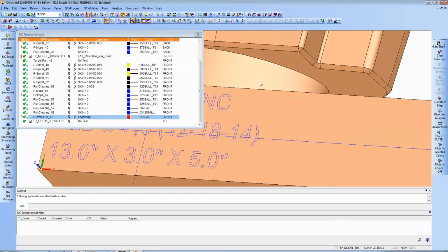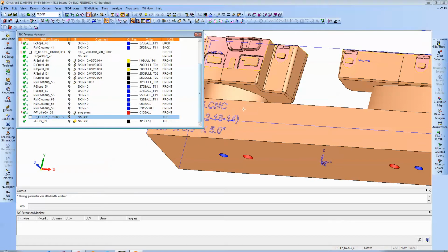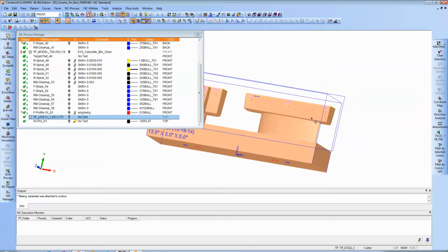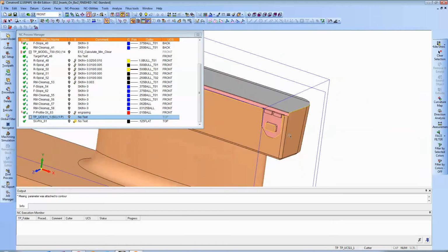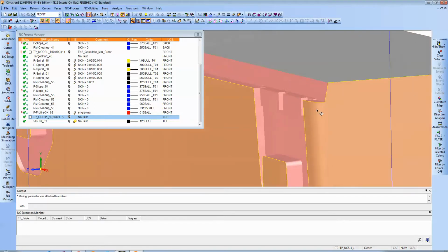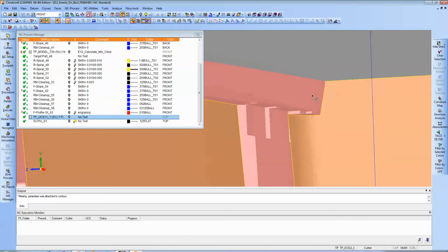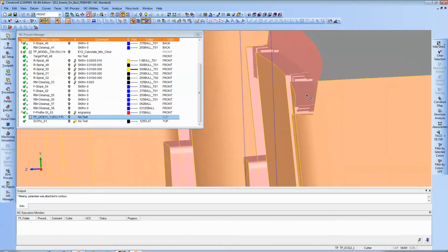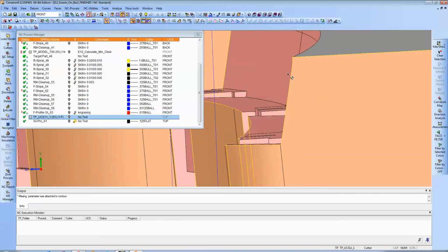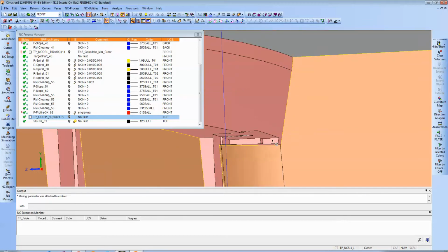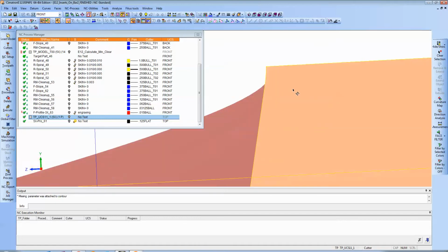And then lastly, on the top, this is of course assuming that you have a 5-axis machine. What I did on the top is I wanted to drag a flat cutter along this face, and I wanted to position the tool 90 degrees to this edge and pick out along this edge. But you can see there's a little bit of an angle change here.